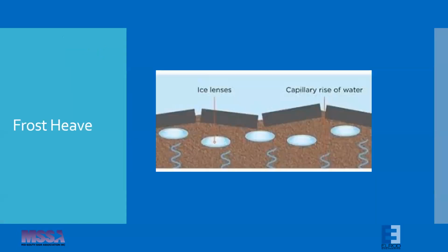One thing I like to mention is frost heave. Pay attention to foundation depths. We don't run into it too much in the South in our region, but if you have a project that's getting up into the upper Midwest or New England or some areas, you can have a pretty deep frost line. So frost heave, if you're not familiar with it, is a principle where the moisture in the soil freezes, and that freezing causes the soil itself to expand.